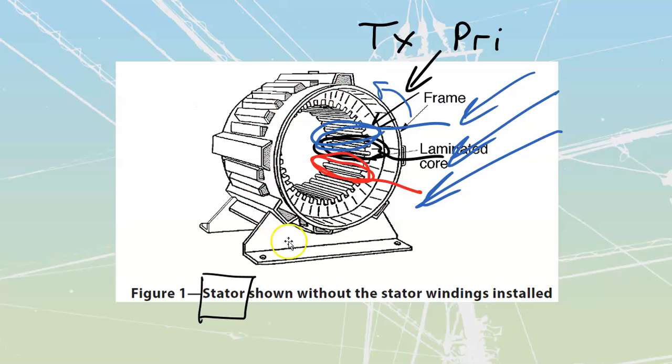The enclosure, how this motor is going to be built, is going to make a difference, though, to the way that it is going to cool. Let's just talk about this. Right now, if I see this enclosure over here, I've got this main frame that I'm going to be mounting everything onto. That frame is usually going to be a solid piece of steel. We're going to want something that is going to carry magnetic lines, obviously on the inside. Sometimes if these are aluminum on the outside, then there will be steel going around on the inside to complete those paths. But then we have to place these end bells that are going to seal these things off. We're going to have varying amounts of sealing. If I don't seal very much, I'm going to get good airflow, which is going to be good for cooling, but obviously it's not going to be great for a lot of my environments.